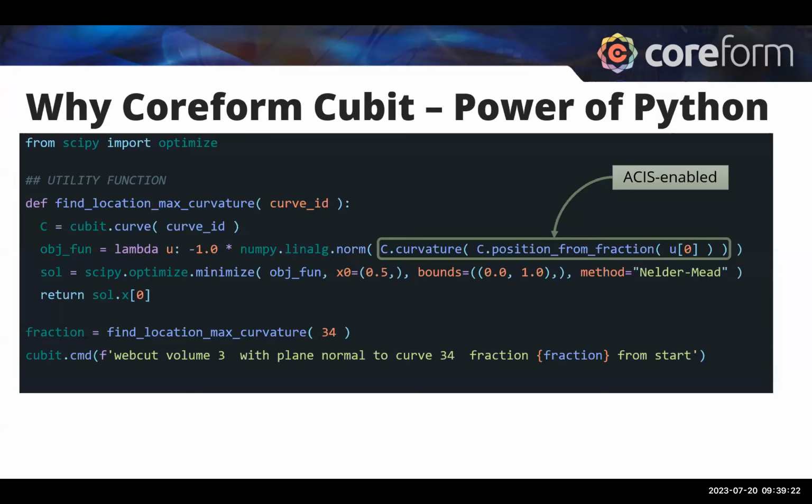The more you have to traverse along a path like this, that can impact performance. The one thing I'll check, that I see in probably 90% of the performance issues with the Python API, is that you're doing a lot of traversing. I would pre-allocate, it's not the right term, but pre-allocate the object that you would then want to evaluate. Just see if that might give you some performance boost.